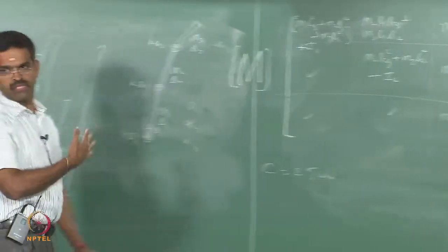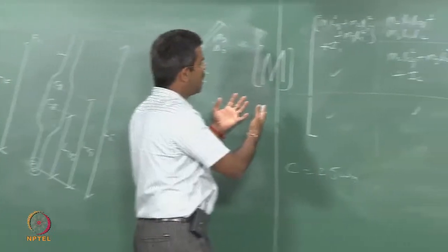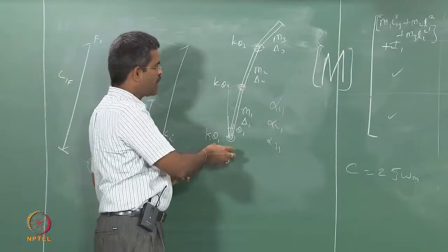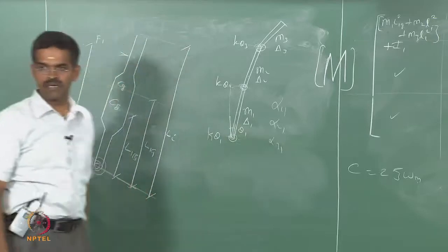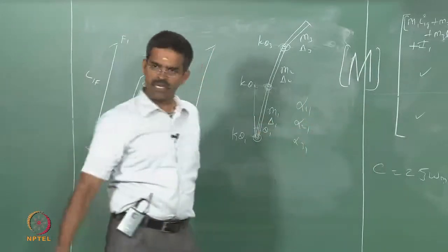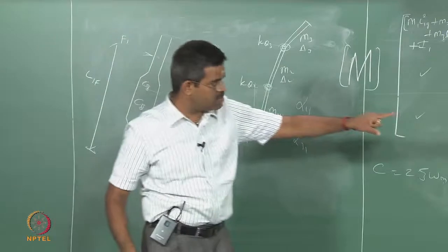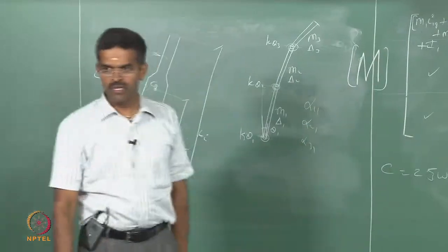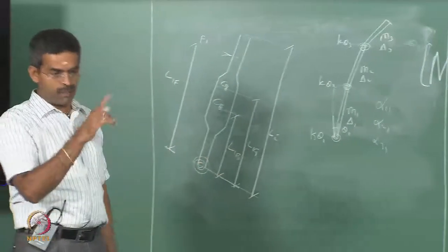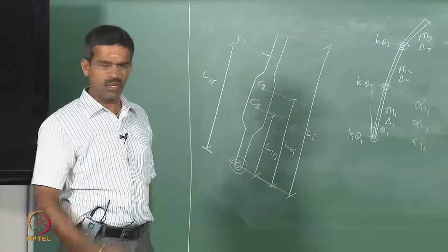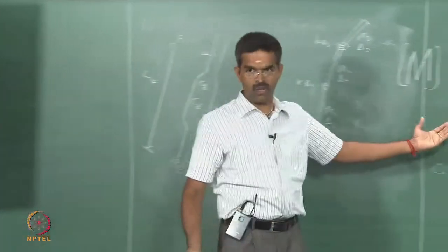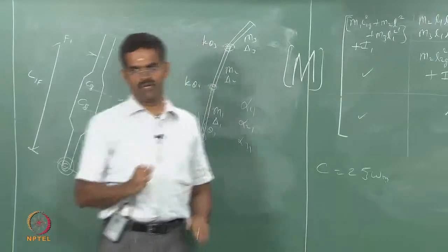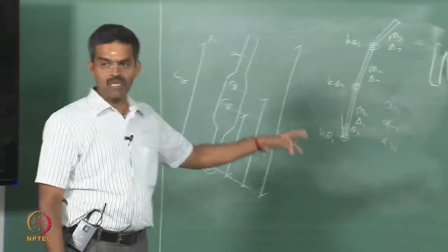Now any doubt here in simulating how we are getting the mass matrix, how we will get the k? I am leaving it as homework for you. You should be able to do this, because if you are able to derive the first column of the influence matrix or the whole matrix, you can easily invert it and get the k matrix, which will be exactly similar to what you have there in theta 1, theta 2 and theta 3 terms, which you will appreciate. If you still have doubt, you can always look at the papers, which I will refer back now. Of course, the derivation is not shown in the paper. You will have only the mass and k matrix given in the paper. You can compare them and find out. But the derivation comes from here like this.